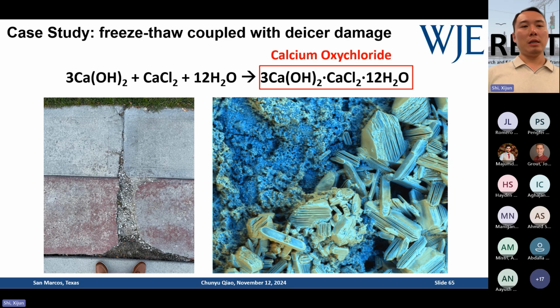It's a salt. So what is the salt? You see these two images here. The one on the left, I took outside my hotel in Chicago 2 years ago. If you have a lot of salt accumulation at the joints, because you have poor draining at the joints, it's a little like a tiny pond. So you have salt, you have water, you have low temperature, you have calcium hydroxide. So a lot of times you have this premature joint damage. So this is joint damage.